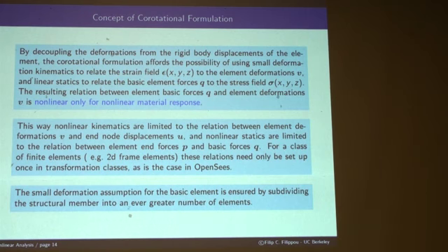Now this is 2-node, 2D and 3D frame elements. So you want to have your favorite 2-node 2D frame element, which is the fiber hinge element, or you want to have a distributed inelasticity element, or you want to have a concentrated hinge element, or whatever you want to have. If you want to turn on rotational formulation and account for large displacement, all you got to do is tell OpenSees that you want to use the transformation class corotational.